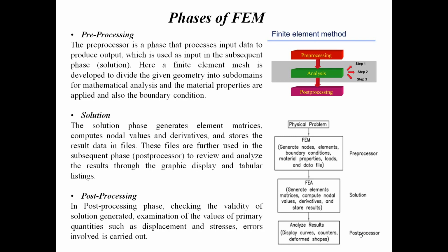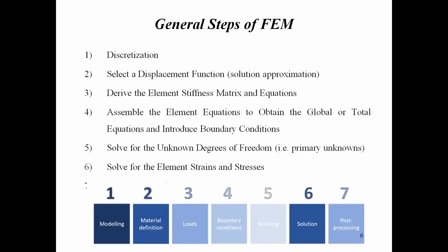And post processing is nothing but the interpretation of the result. So how the results are required, in which form you require the results, that is nothing but the post processing. The most famous technique in the FEM is the contour plots. So we will get the results in the contour plots. It is shown in colored shapes. The colored portion indicates where the stress or displacement is maximum, intermediate or minimum. So we will get that result in the post processing.